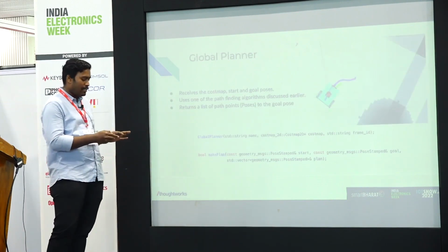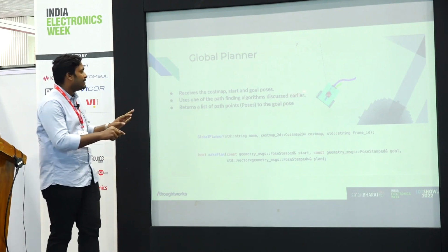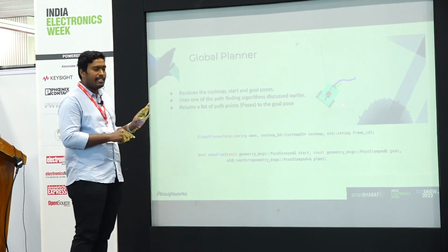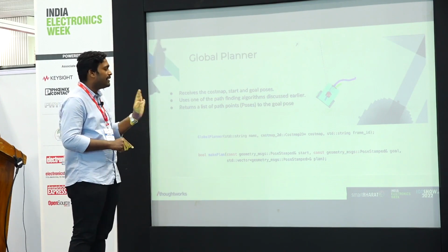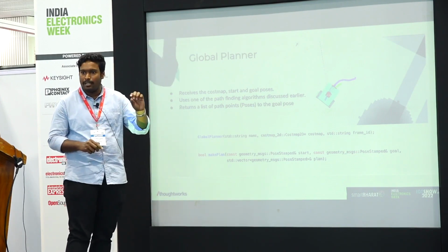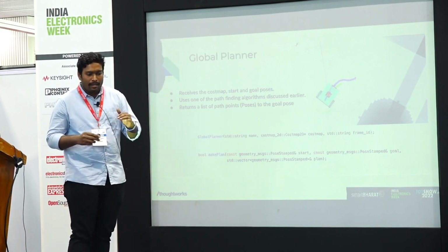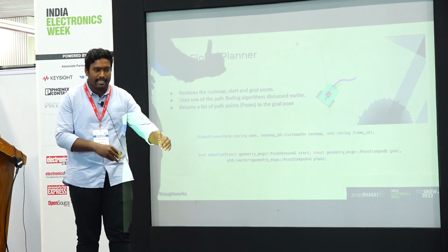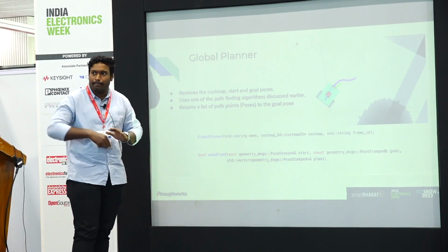Next is what you actually see. This is a simulated robot. It's a differential drive bot, and you have this pink color path, which is the global path that's generated for a particular target location. And this is your local planner generating a path for a smaller area. It's not going to compute the local path for the complete environment.